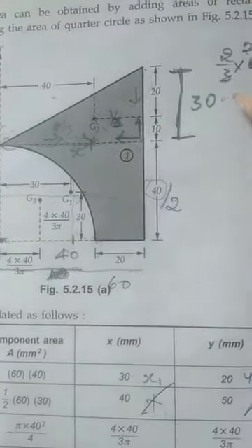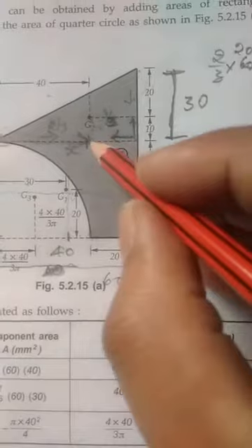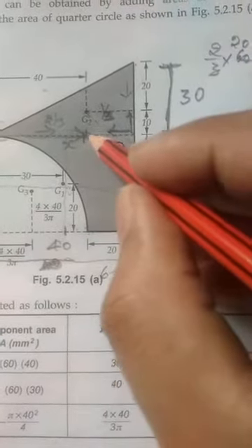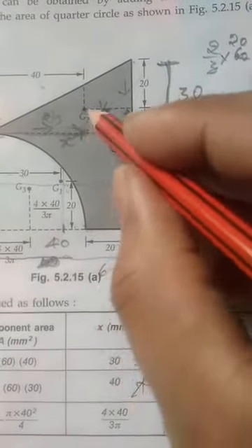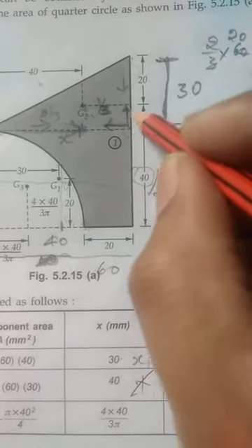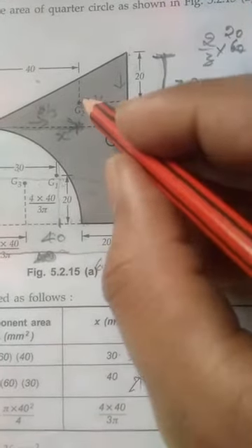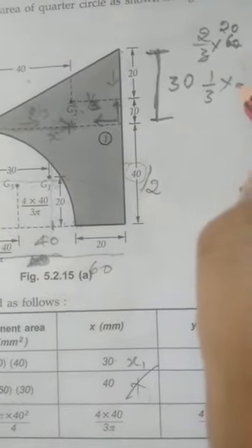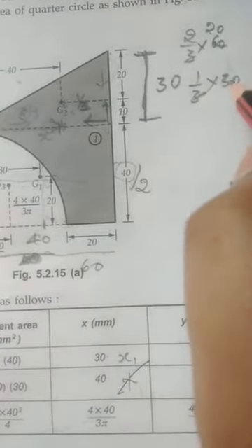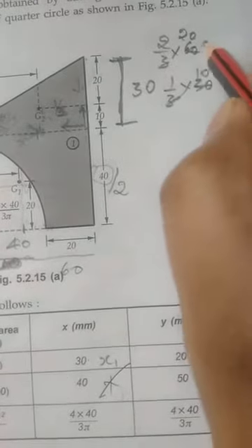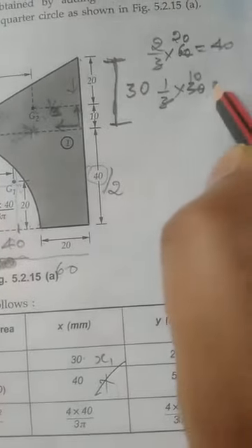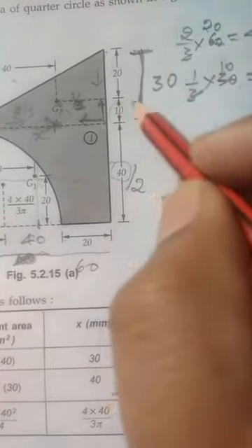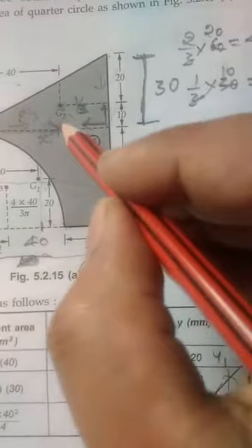Here it is written. Okay, so next is the distance from here to here. From here to here it is 40, plus what is the height? This is the height you have to take. So from here to here it is 1/3, and 1/3 of the height 30 is, if you cancel it, 10. So this is 40 and this is 10. The centroid distance will be 10. It is written here.